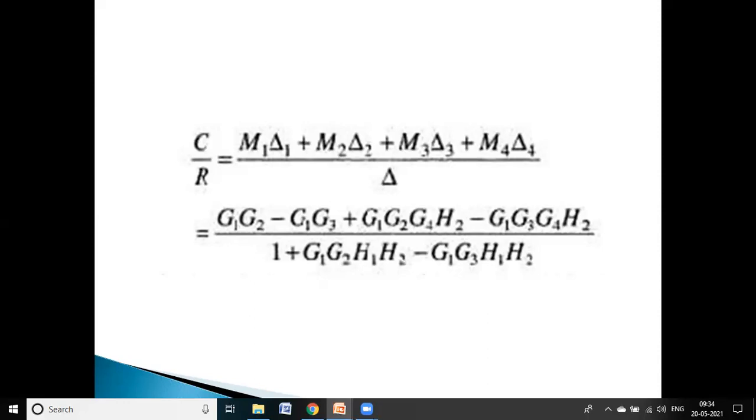Similarly, signal flow graphs can be represented in different forms. It is not unique, whereas the final transfer function is the same. Even if we use Laplace transforms to get the transfer function from the mathematical model, finally you have to get the same model.